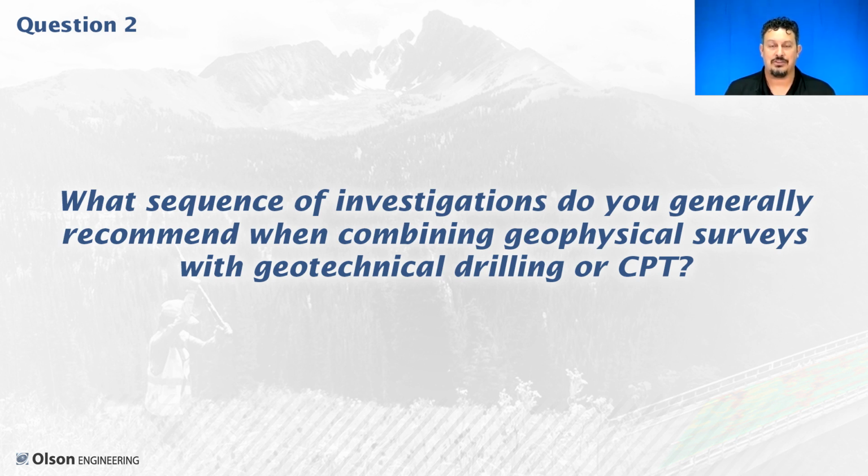Then I would go back with the CPT survey and do a number of pushes in the areas where we expect a defect of some kind, or subsurface flow, anything that could be of interest. And then if we want to refine in any of those areas, I would probably then do a resistivity survey as the last approach, but just focused on the areas where we need to refine our understanding.